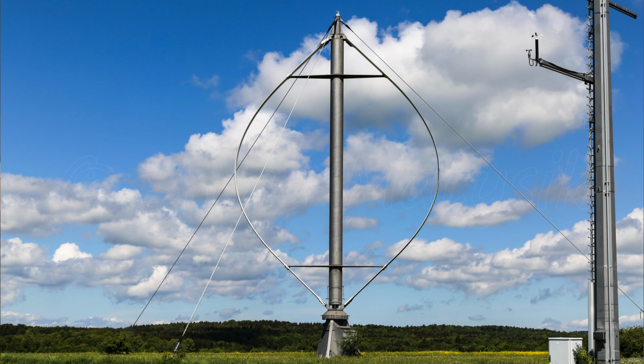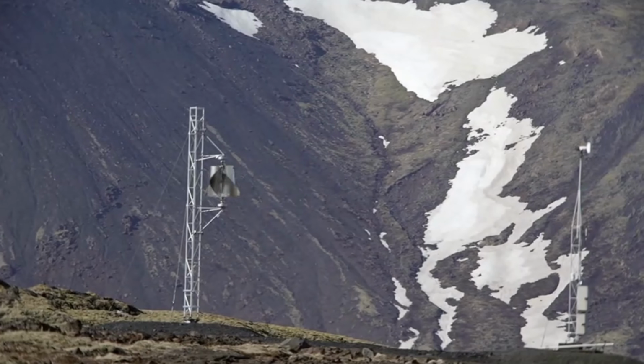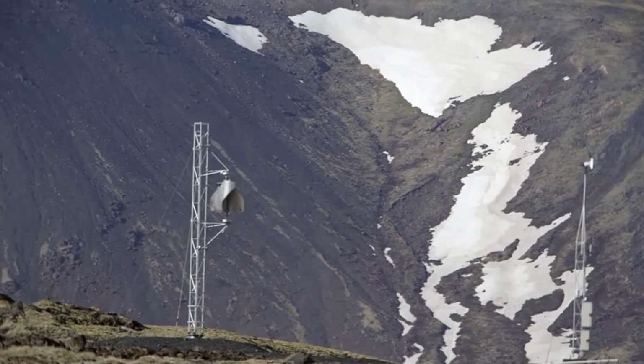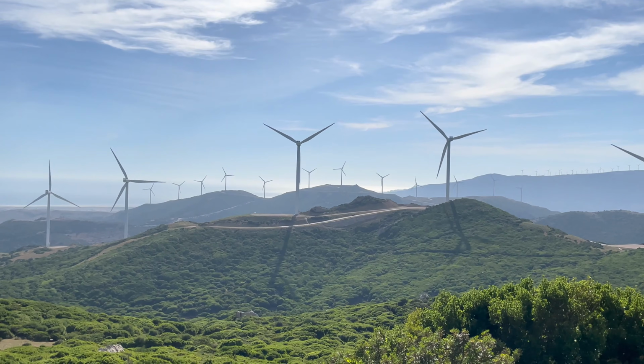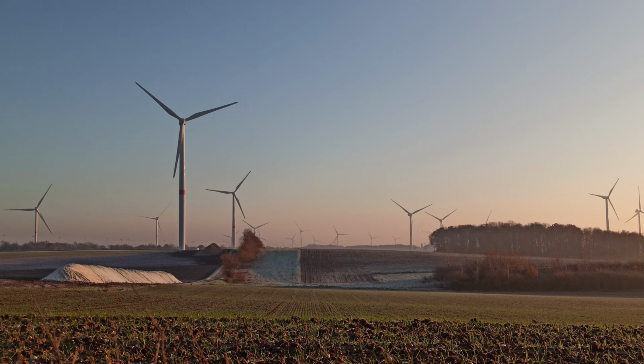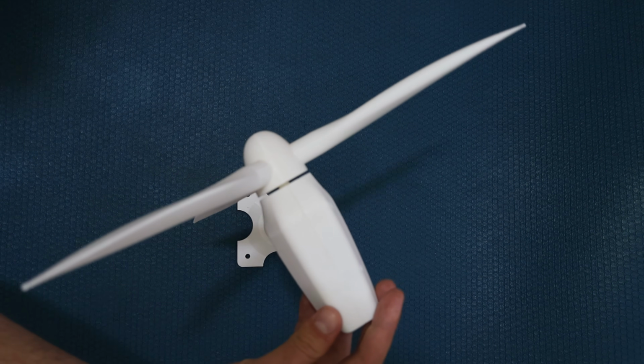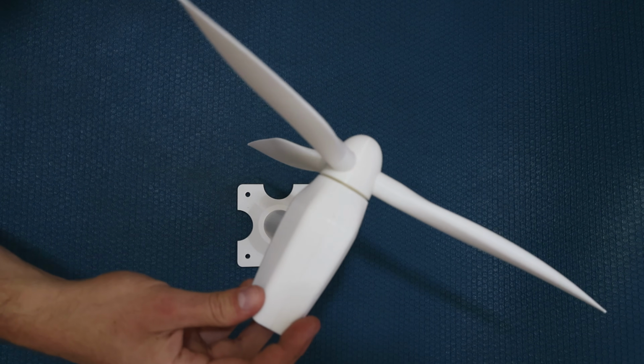Their main advantage is that they are installed closer to the ground than a horizontal axis turbine. Being closer to the ground is advantageous in areas with variable or inconsistent wind patterns. Because of this design feature, they could capture winds coming from virtually all directions, unlike the restricted horizontal axis turbines. Albeit, horizontal axis turbines are able to adjust the yaw angle to face the wind, but not with the same flexibility as vertical axis turbines.